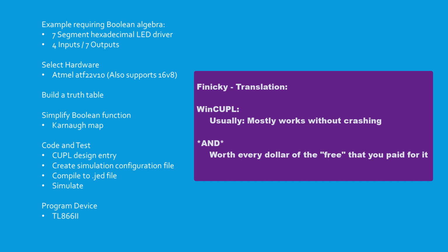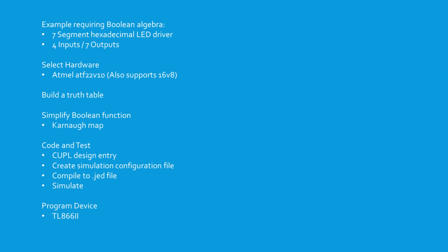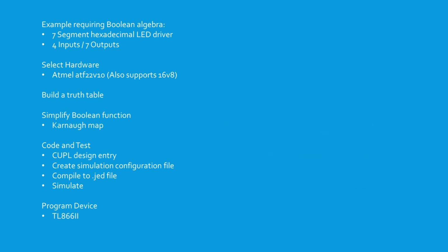After successfully compiling, I will demonstrate the simulation feature before we commit the code to the PLD device. Lastly, we will program the device using the inexpensive and widely available TL866II Plus programmer, put the chip in our breadboard test circuit, and demonstrate the functionality.